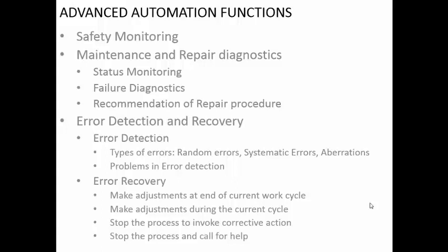Failure diagnostics means determining the reason for the failure. You can write a lot of programs to determine what exactly has failed. Maybe a motor has stopped, a motor has burnt out, or maybe some switch has tripped because of excessive current being drawn. So failure diagnostics will tell where exactly the failure has happened, because of which the entire machine has stopped.